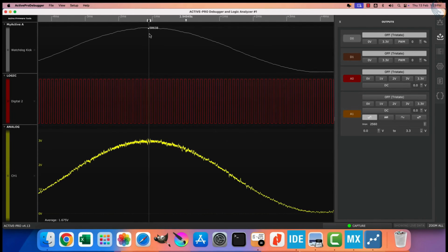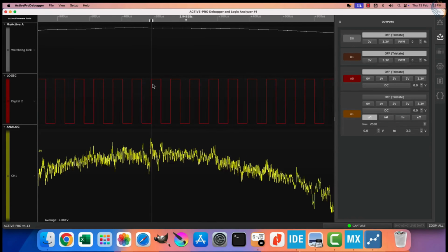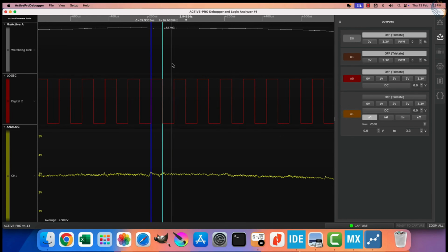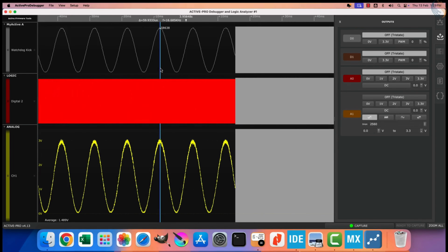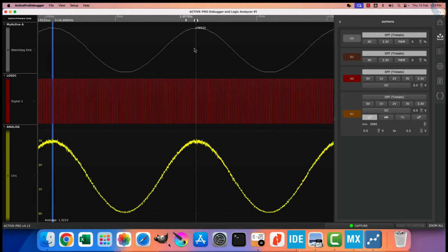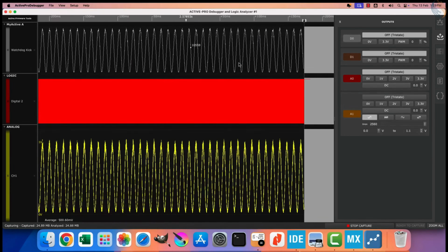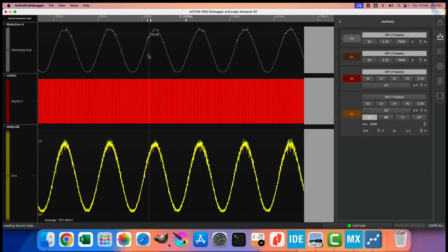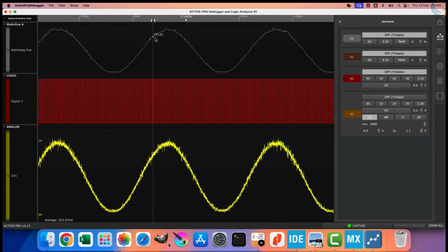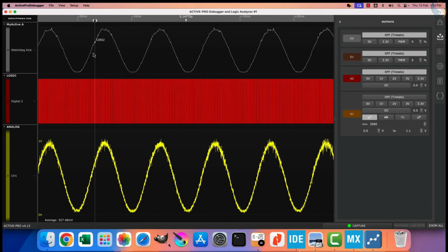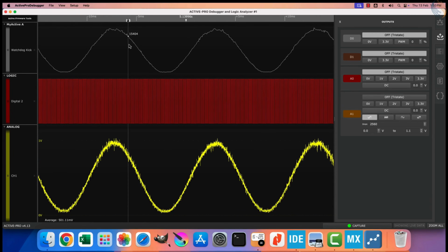Let's capture the data again. You can see we still have the 16 bits resolution. Also the pin is toggling every 60 microseconds. That means we have the same sampling frequency, which was prior to the oversampling. Let me change the voltage back to 1.1 volts, and capture the data again. We are now getting the maximum value of around 19,000, which is near 1/3 of the maximum 16-bit value. But note that the output data still has jitters, even at this resolution.